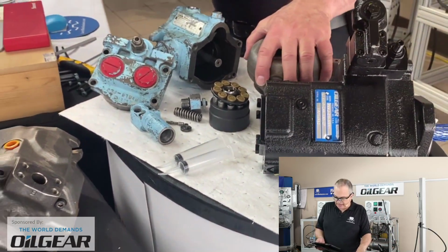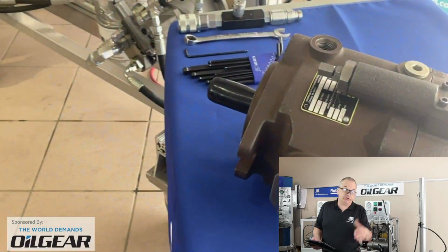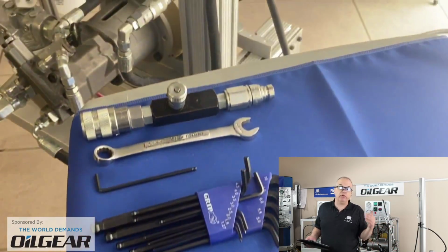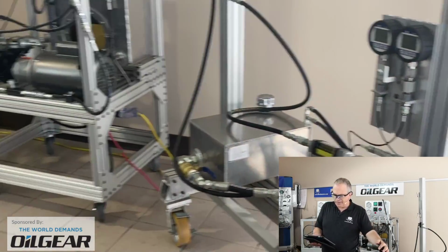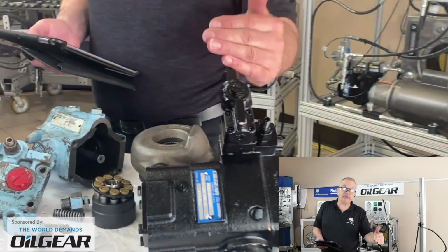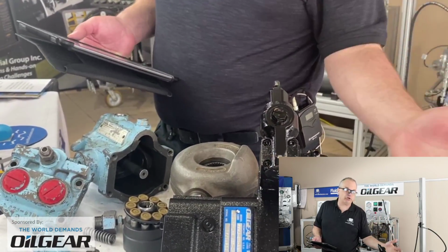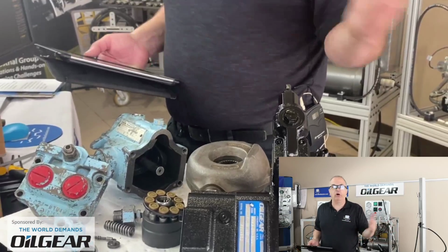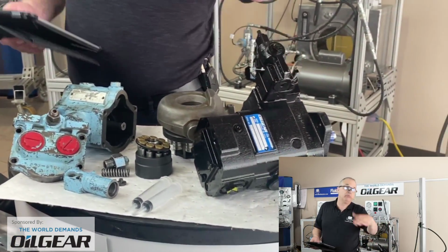So those are very advantageous, especially for long times when there is no call for pump flow in the hydraulic system. I hope I answer that. It's not necessarily critical if the manufacturer has determined that the pump will cycle on and off and use flow on a continuous basis. Different designs.